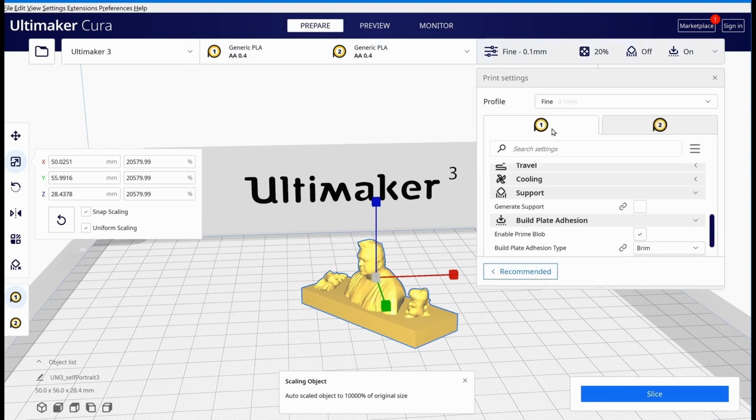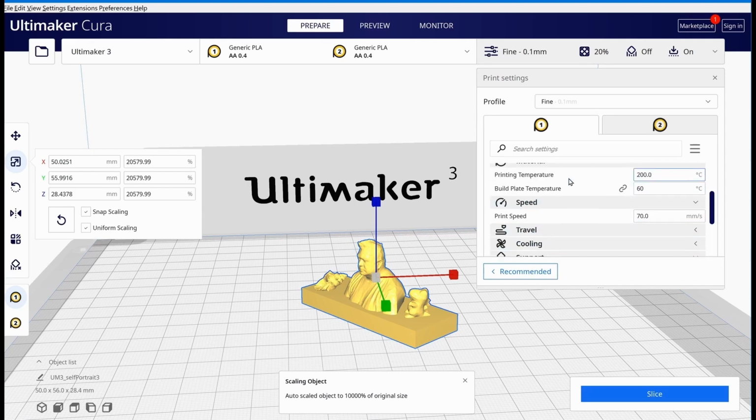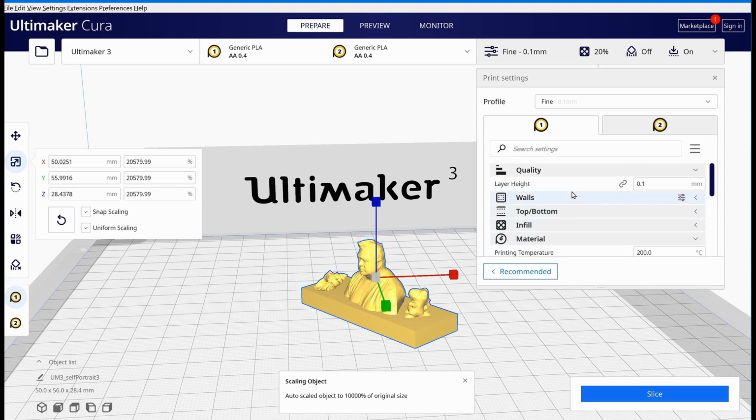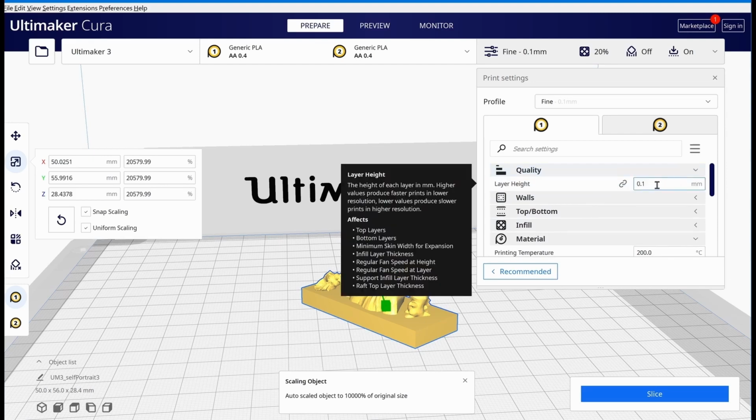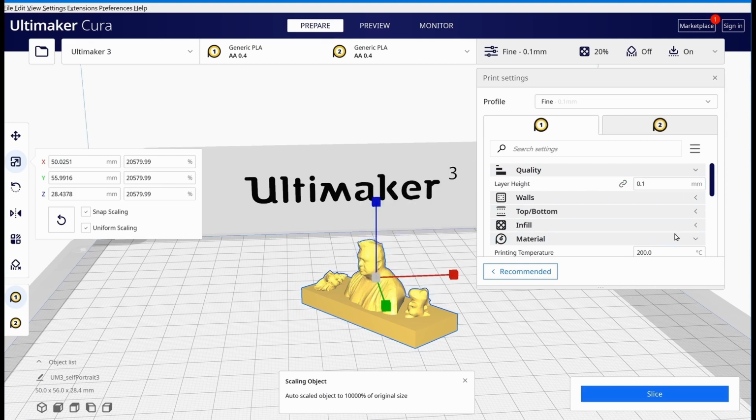And so if you submit your file to FabLab, they will do all this because they will base it on the correct 3D printer that they will use. If you're going to do this on the lab computers, this is where this part matters. Some things you just don't change. I don't have the exact variables for every piece, but I'm going to choose 1 millimeter layer height, which is fine.